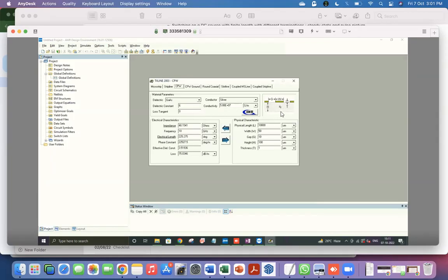The only difference is in CPW, there's no ground plane at the bottom, and it's giving me 50 ohms, and CPWG is giving me 48 ohms. Does that make sense? Why is that? Higher capacitance, because now you have an additional mechanism for getting capacitance to ground. Okay, it's not a very big difference, but it is still there. So what I'm asking is, under what condition will these two give you the same number, or a very, very small, insignificant difference, even smaller than what you're seeing right now?